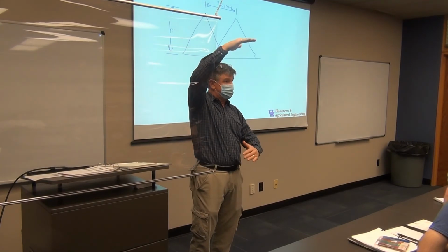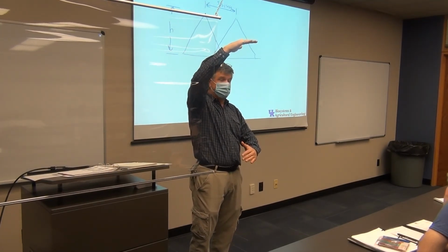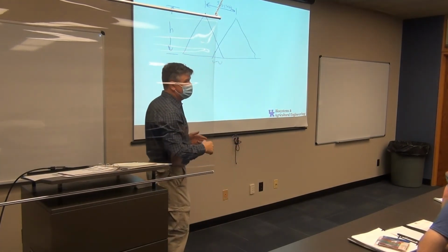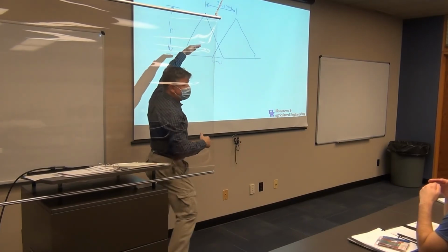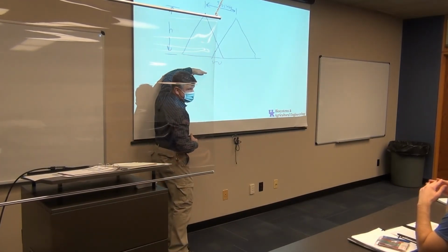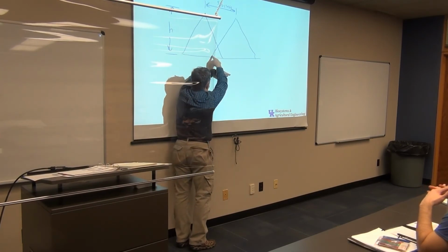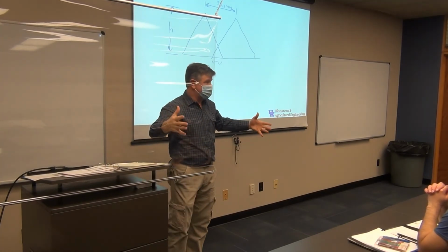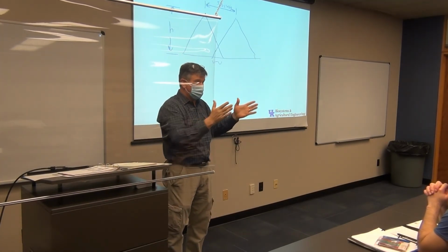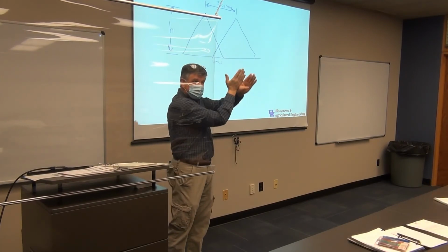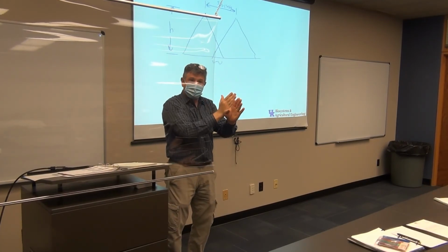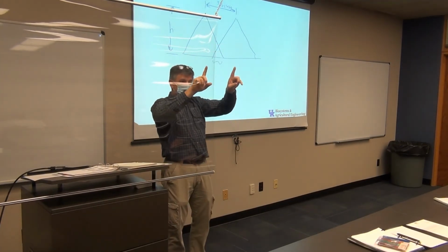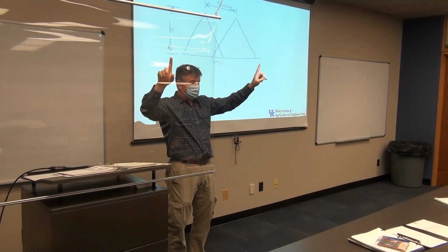Yeah, so if the height goes up, if my boom goes higher, what do I have to do with the nozzles to maintain that same overlap? So if the boom goes up, that'd be the same as moving the ground down. Think about moving the ground down, right? So move the ground down here, that's going to bring these patterns coming over here. There's going to be more overlap. And now I'm going to lose my uniformity. So I'm not going to be at my optimum CV. That's going to move me one way or the other on that CV chart. So if the boom goes up, my nozzles got to go out.